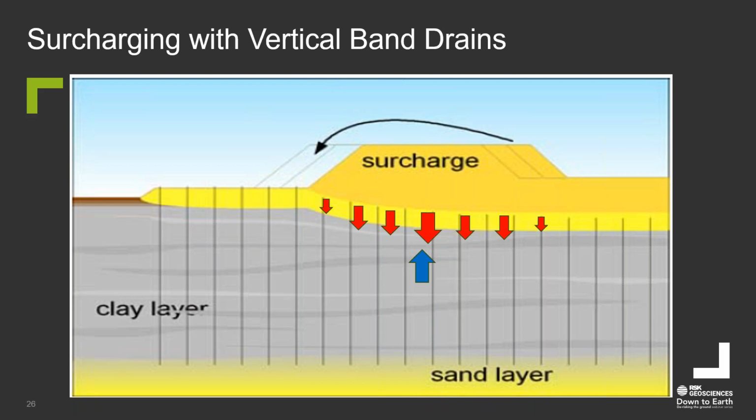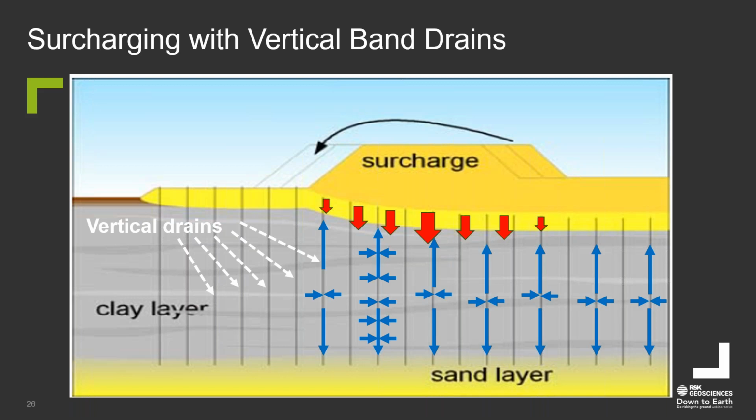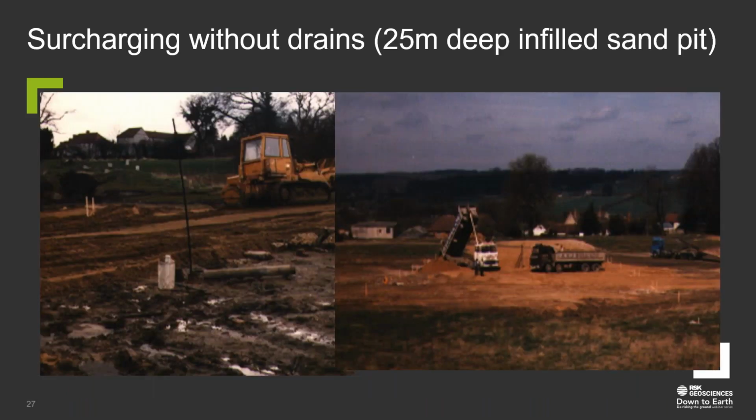And what we need to do with that is somehow apply vertical drains in the soil and make the water within the clay void space get to the drain, and it'll get there by going laterally and then vertically. And if it's going vertically, there's an equation that simply says the distance it has to travel, the d in that term for time, is squared. So there's a huge time delay if that distance becomes bigger. If you go for the radial direction, flowing to a vertical drain, it's got a much shorter distance to travel, so the time becomes much smaller, is what I want to say on that.